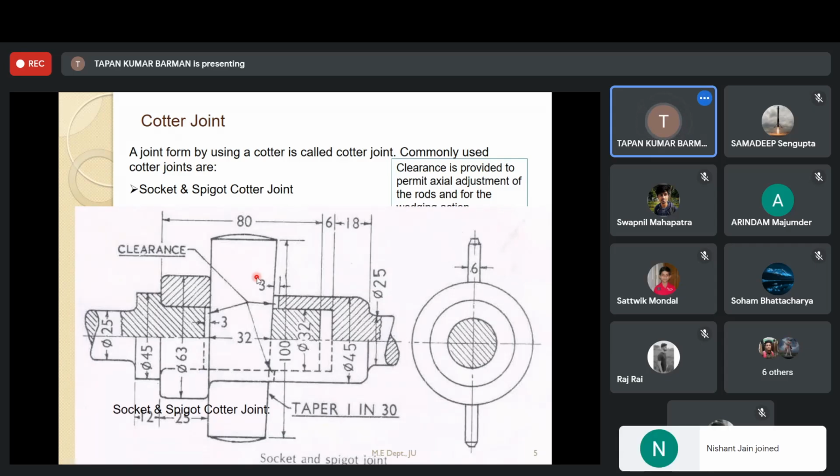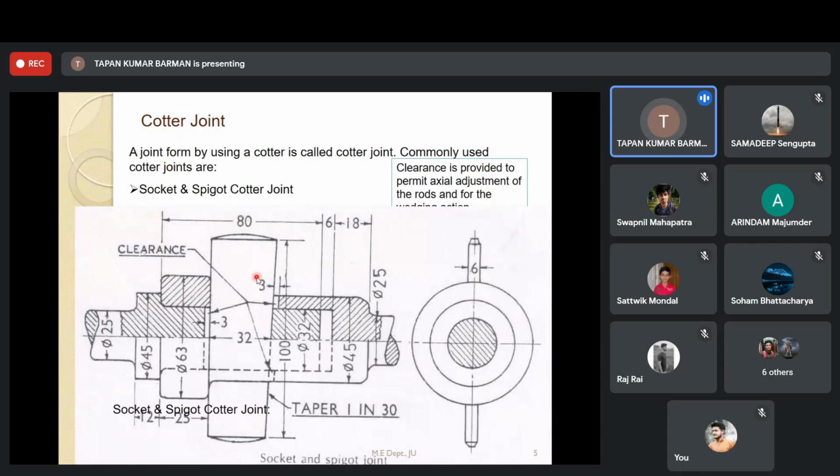When we put the cutting plane, in section we need to provide one cutting plane. That cutting plane is basically imaginary. We pass that cutting plane through the object and remove one part, not physically, but we visualize the object and take the projection of that component.